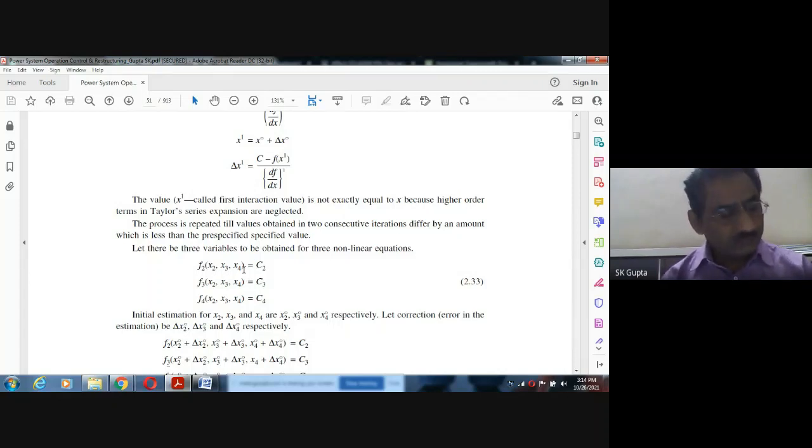In your case, the equations will be functions of p, q, v, active power, reactive power, and voltage or angle. There can be four variables and a number of equations, two equations at each bus. If there are 20 buses, there will be 40 equations, except for the slack bus, so reducing the slack bus. The number of nonlinear equations might consist of sine, cos, theta, etc., but here similar types of nonlinear equations are there. This is some constant value.